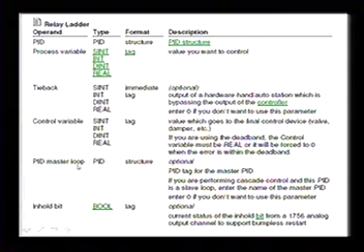Then you've got your PID master loop, the actual instruction itself. And if you are performing cascade control, again, cascade control is when you put a PID in front of a PID, and then you've got some type of a slave loop. And this PID is a slave loop. Enter the name of the master PID, enter 0 if you don't want to use this parameter.